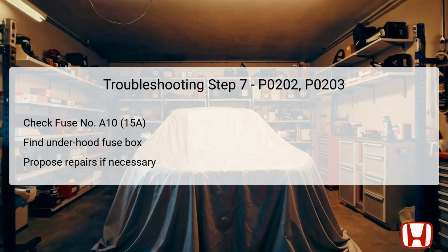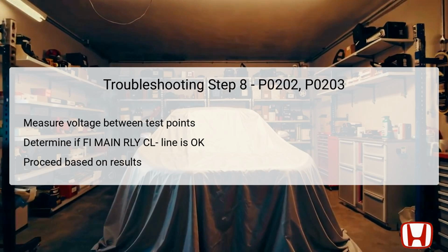If the fuse is intact, again, look for possible opens in the +B INJ wire. If found to be blown, repair shorts in the wire. Replace the A10 fuse and ensure the system is restored properly. For this, while in on mode and the injector relay disconnected, assess the voltage between two specific points in the injector relay 4P socket. These points are 7 and 8 within the socket.